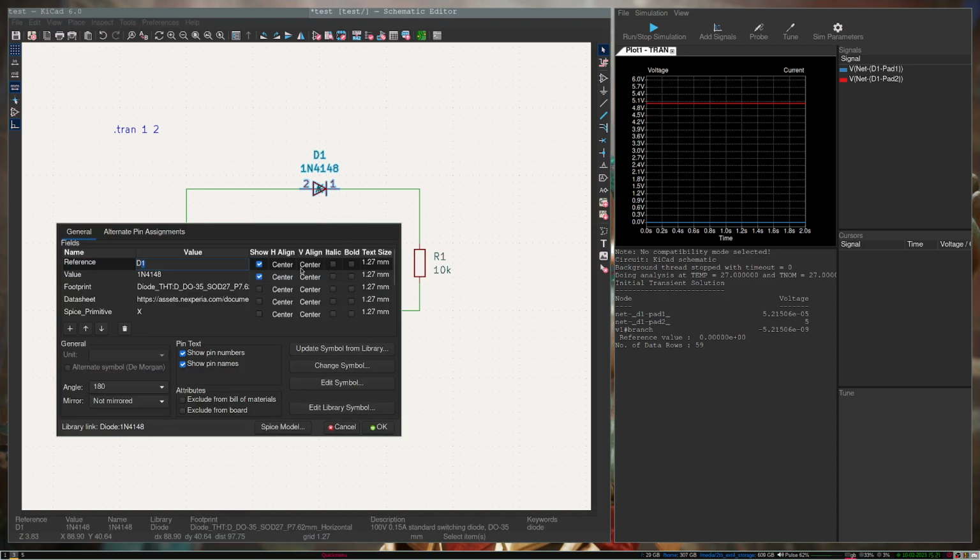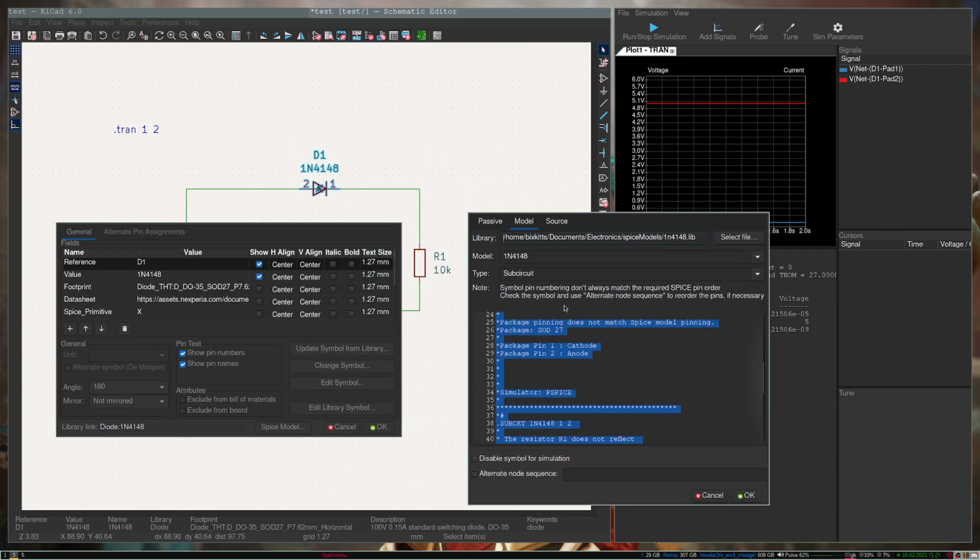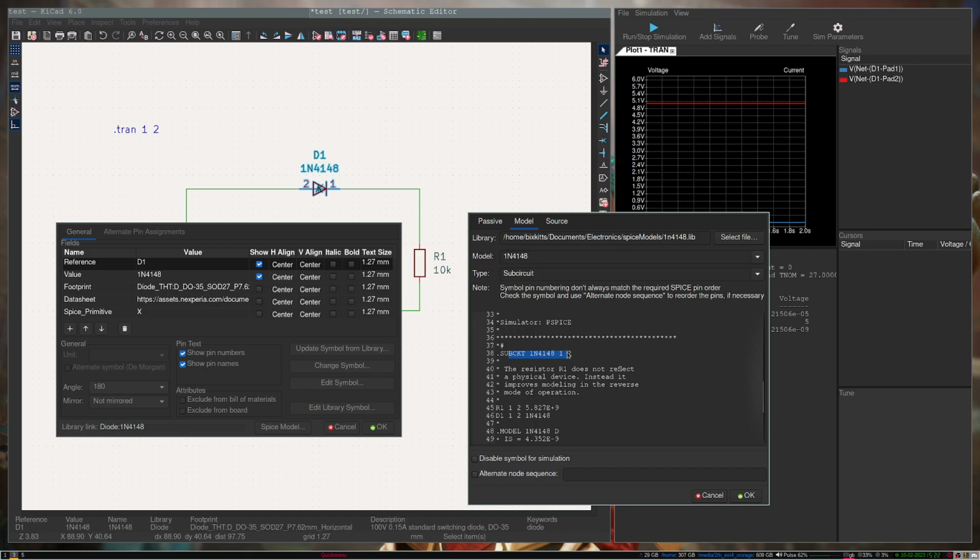output is pin 1. But when we look at the Spice model under this line that I mentioned earlier, under subcircuit, you can see that it orders its pins probably in another order. Usually, under the subcircuit, if you're dealing with an op amp or an IC, it'll actually list the names of the pins and you can match it up properly. But here I'm going to have to assume that what we got here on the schematic is laid out backwards to what we got here on the subcircuit line.